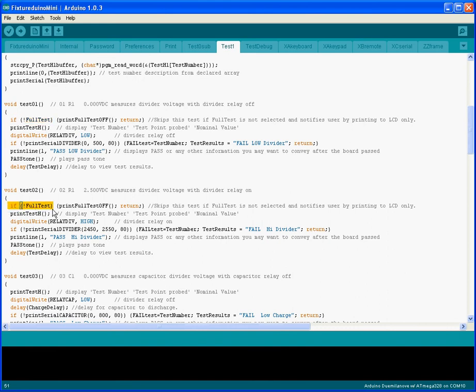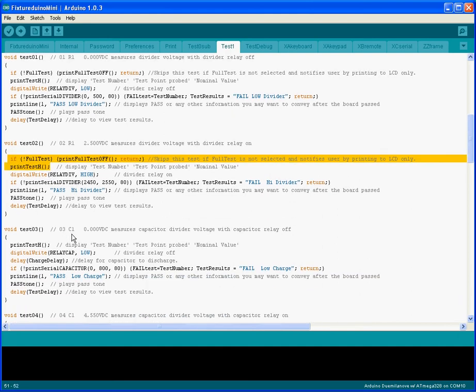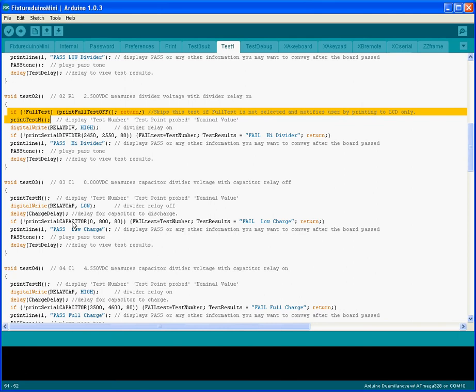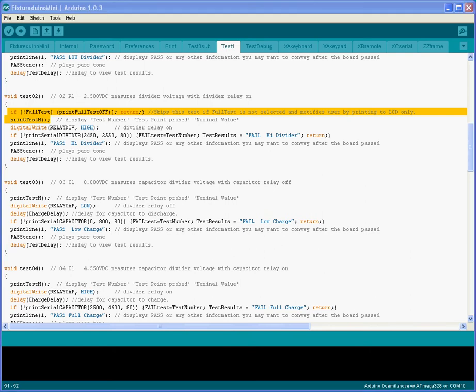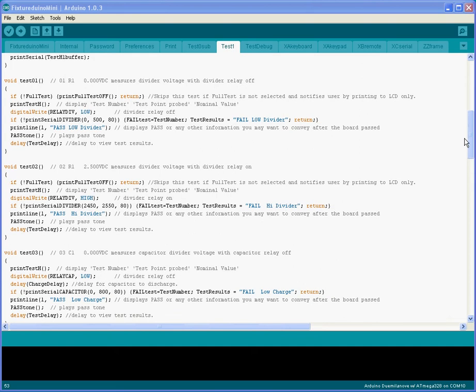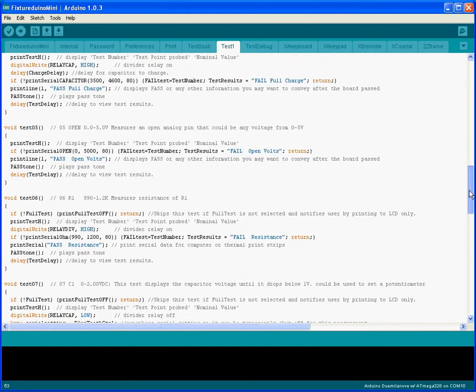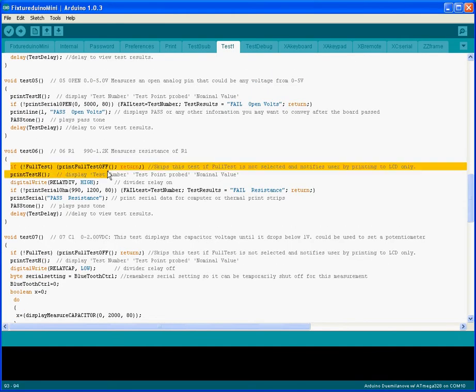There's a full test mode and an AQL mode, which is acceptable quality level. A few tests that we consider might be reliable, such as resistors, are skipped in an AQL test, which allows you to speed up testing on tests that you only might want to make, say, 1 out of 100 times and skip 99 times. Or whatever your acceptable quality level is in your ISO standard, if you're using ISO. So that's what that is all about.